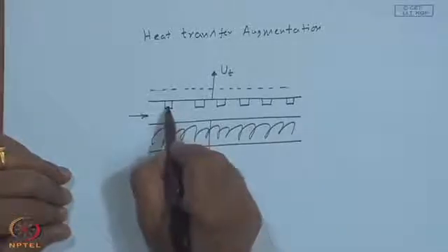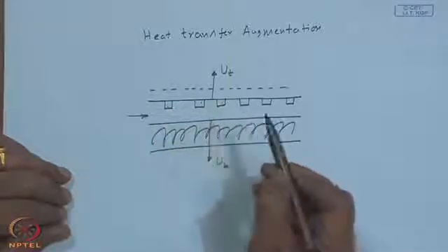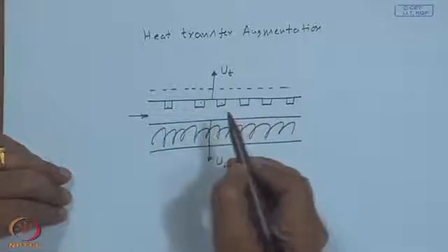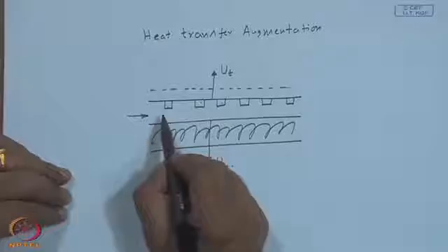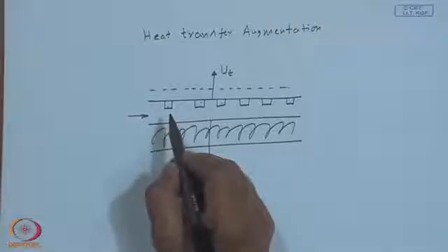Now, these protrusions provide the breaking of the boundary layer or flow mixing, thereby enhancing the heat transfer coefficient.